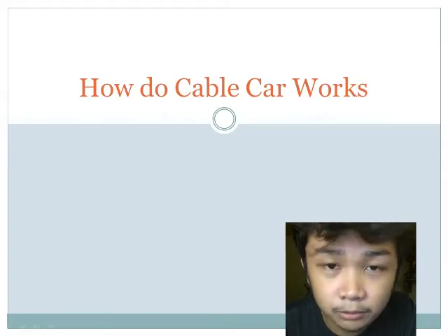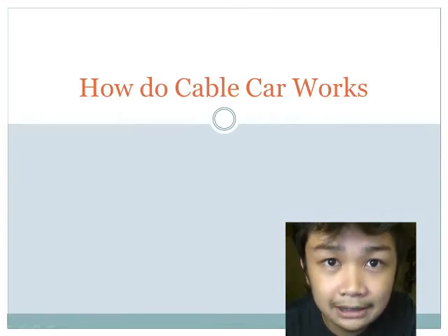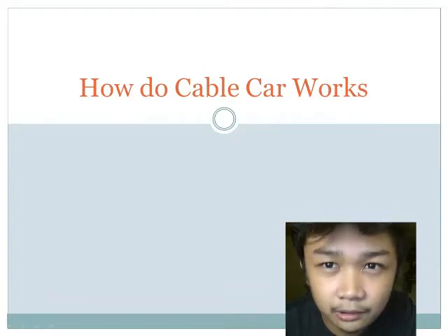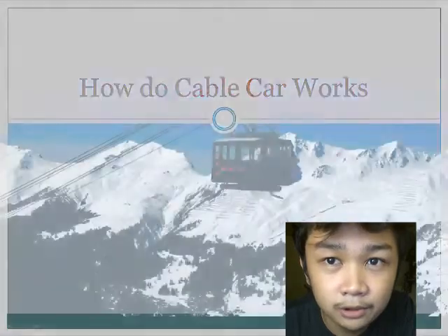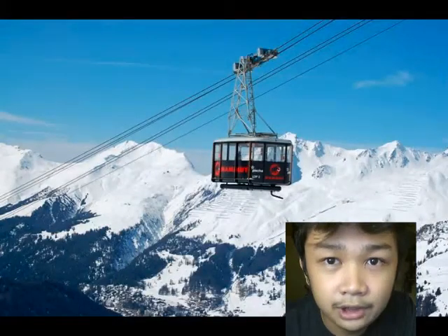There are powerful electric motors that drive giant winding wheels that pull the cables. Each cable has its own set of winding wheels. The rearmost winding wheel in each is adjustable. When a cable is new, this rearmost wheel is close to the other winding wheels. As the cable naturally stretches with use, the wheel is gradually moved back by shop workers to keep constant tension on the cable.